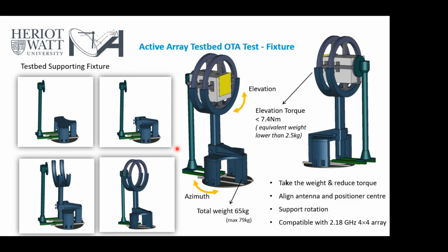And here is the fixture designed by Samuel. You can see here that originally this is what we have as a positioner, and we're adding a base to take the weight. If you don't do that, then the small plate will take all the weight, and it can maximally only take 2.5 kilograms.